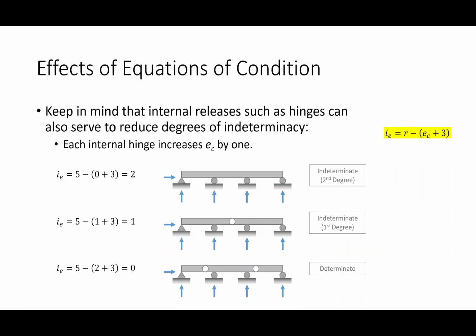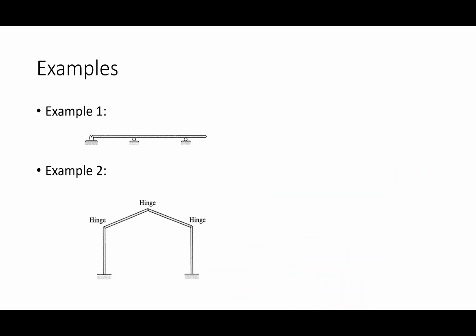The reason why is because if I break out my samurai sword or lightsaber and cut right through that hinge, I know that the internal moments at that point are 0, because that's what a hinge is. The equation for that condition is that the sum of moments is 0. So this is how engineers back in the day would take a 3-span bridge and make it solvable. They would just throw some hinges in there. Does that make sense? So far, so good? Let's do some examples.